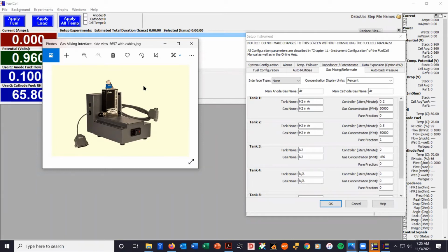When you switch back to a carbon monoxide free environment, typically it's carbon monoxide in hydrogen. If you're doing CO poisoning and you want to switch back to CO free pure hydrogen testing, it takes time to purge all of that adsorbed CO out of the system.